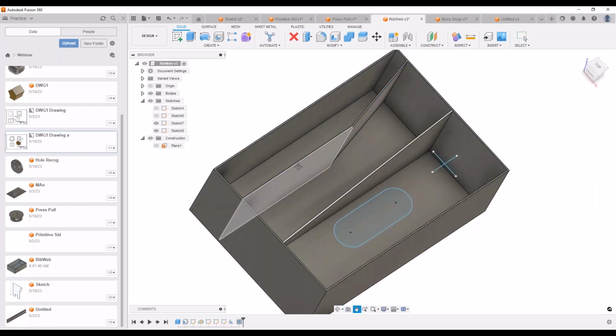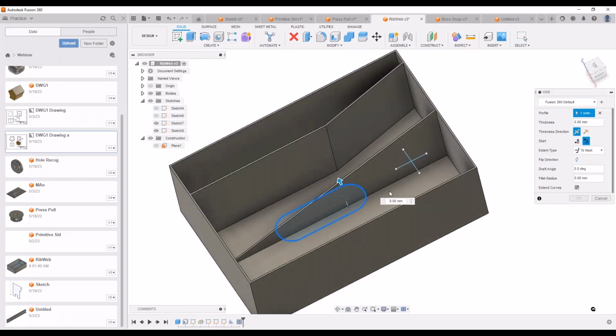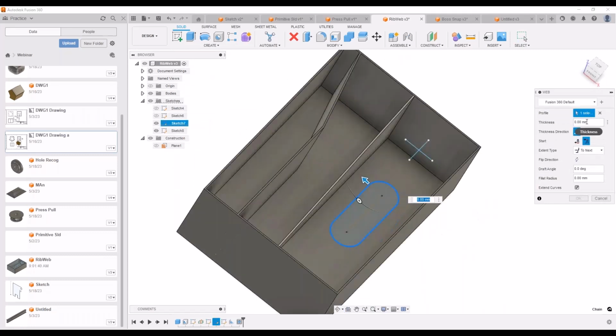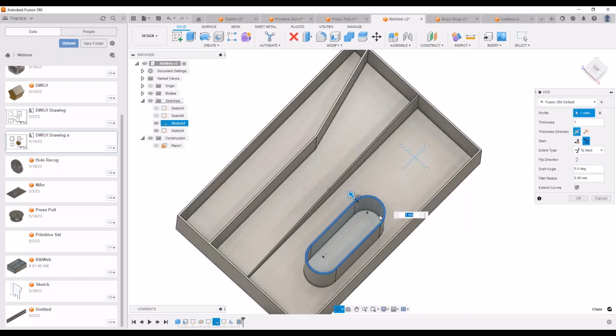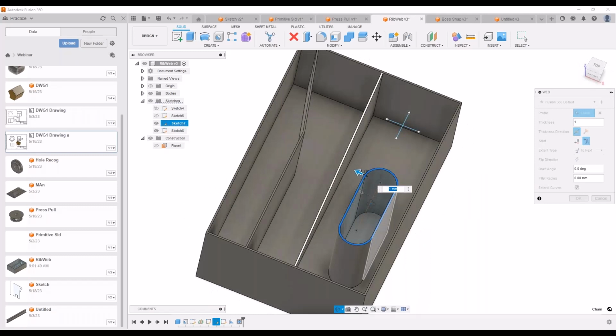Another thing that you can do with web is very interesting, very cool, is if you hit the web and you look at that little section over there, you can make any shaped gusset web or with any form of thickness. I mean, obviously within physical limitations, gussets like that as well. So you can go and make any form of profile and create a gusset, a web, or a rib on the inside of your tool in that way. So between the two tools, you've got a large list of options and capabilities that the software has to suit the design intent that you may have.